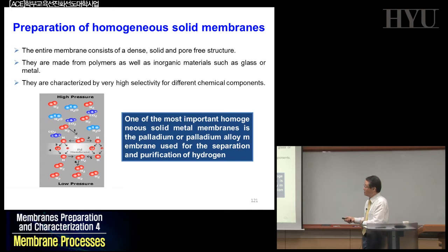You have the hydrogen molecule with the CO2 molecule and water, and hydrogen is much smaller than the carbon dioxide and water, so that the hydrogen molecule can be ionized on top of the palladium interface, and these ions, protons for example, could be transported through this palladium metallic layer and will be again associated on the bottom of this palladium membrane to become molecules.